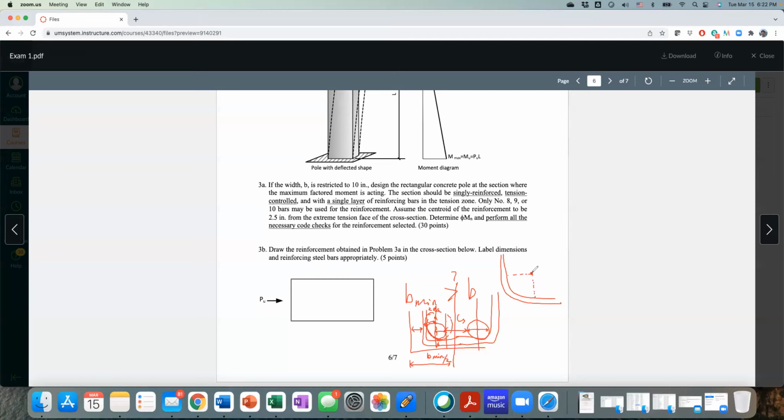So when you bend it, it's actually a bending machine, and there's a big giant steel disc that your bar is wrapped around, and then you bend like that. So that radius from the inside wall to this is called the center, right? The bending center here is two times the diameter of the stirrups. That's where the 2ds is coming from.